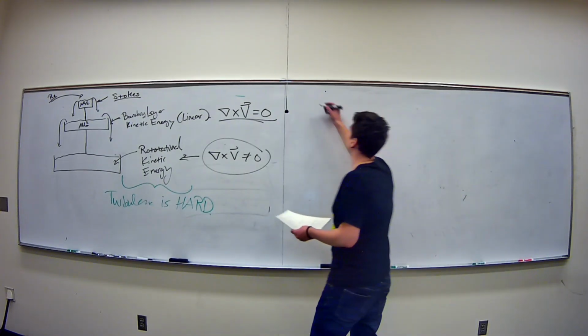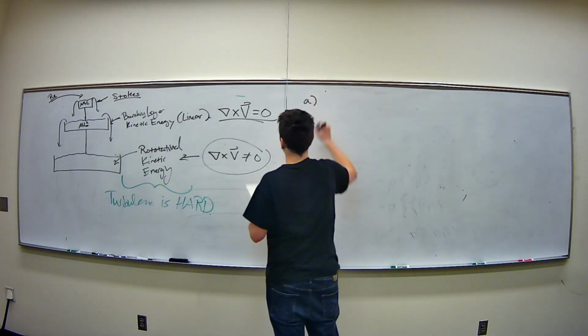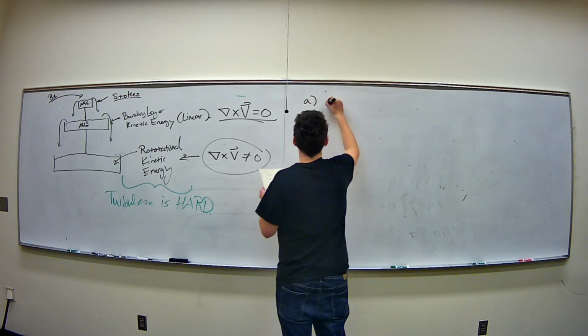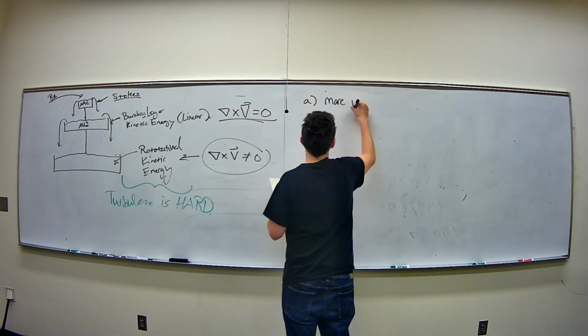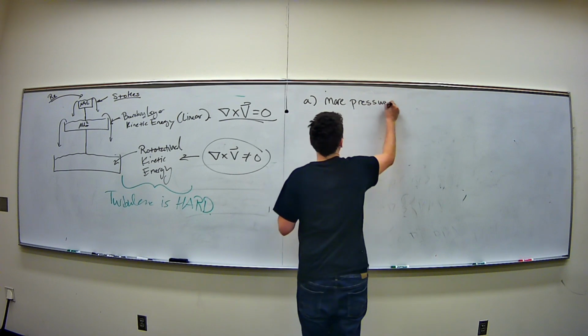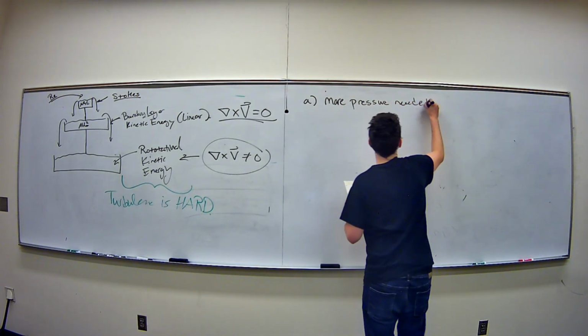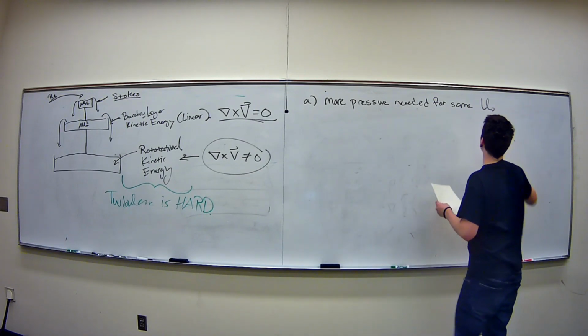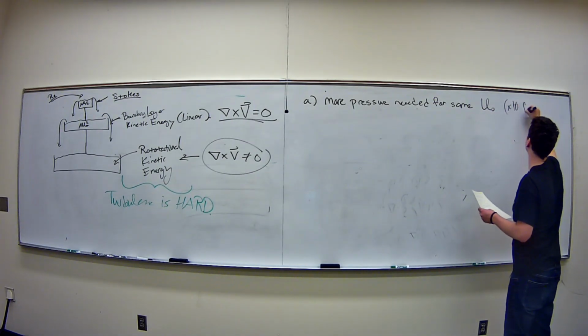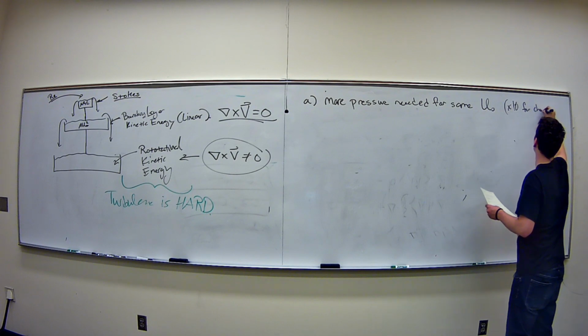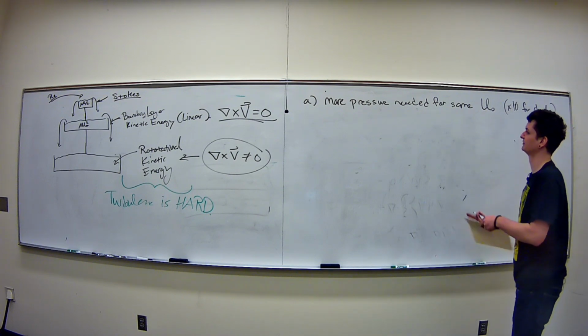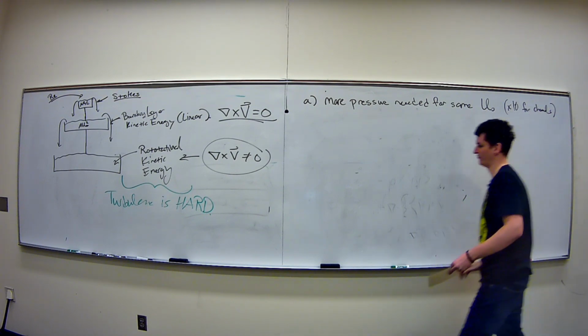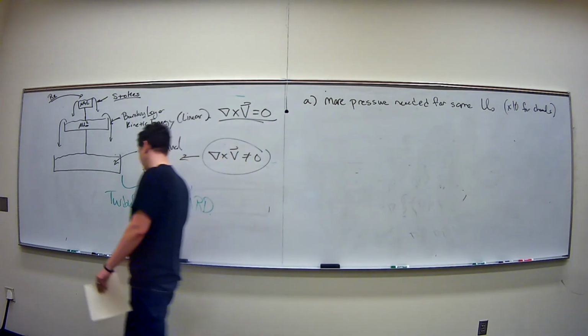Okay, so the takeaways, things that you're normally going to get from more analysis on here, one about turbulence is there's more pressure needed for the same flow. And this is about 10 times for channels. More pressure is needed to drive one speed of flow in turbulent flow.